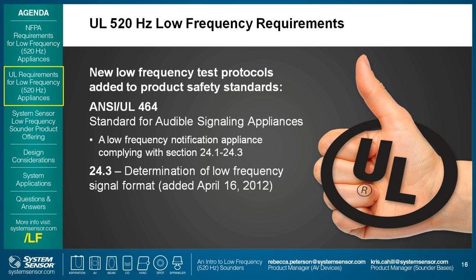And the reason why I'm focusing on this standard in particular is because this is the only standard that allows for a general evacuation tone if it's listed for a public mode listing, meaning that most of the other standards, let's say for the smoke alarms or smoke detectors or carbon monoxide alarms that have some sort of an audible component, are normally listed for just a local notification. So you're not allowed to trigger a general evacuation based on that device. Only if those devices are listed to ANSI UL 464 can you do that.